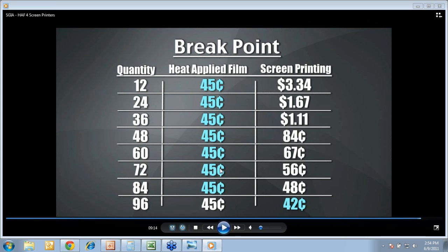Likewise, if you've had the rule to date where on stretch fabrics a lot of shops only screen print them, I think with this new heat-applied film, it makes total sense to use a heat press for stretch fabrics because it stretches and because it has the low temperature range, so it doesn't give you that heat press box on the image. Also, it only takes 8 seconds to apply, so it's not under the heat for very long.